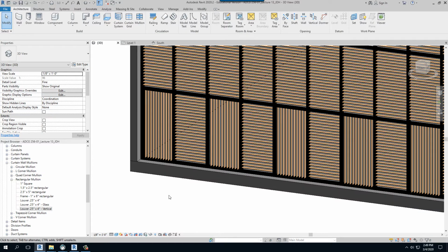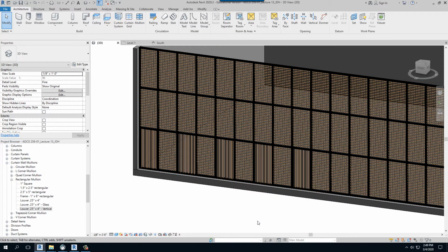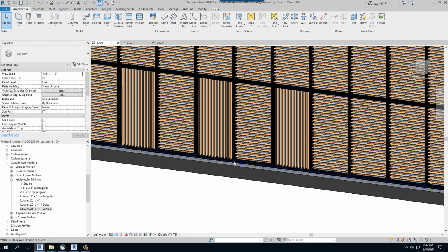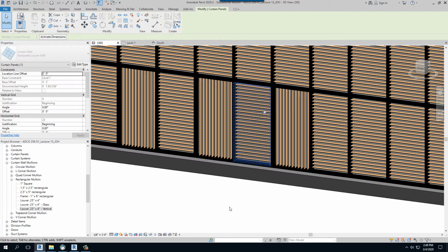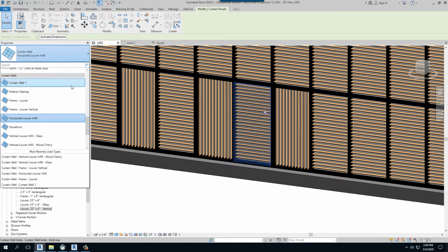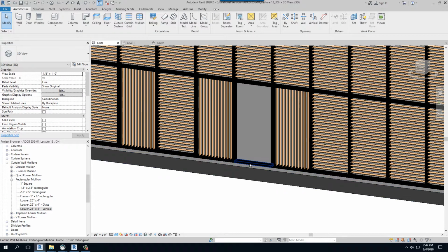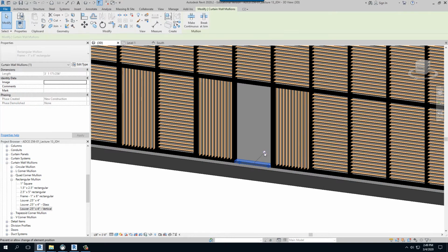One thing that we probably didn't think much about is, wow, how are we going to get in this little facade wall here, right? So just like anything else, I can come in here between these two verticals, and I can click on that panel, I can unpin it, and I can still say make that an empty system panel. Then I can delete this down here, and now I have an entry.